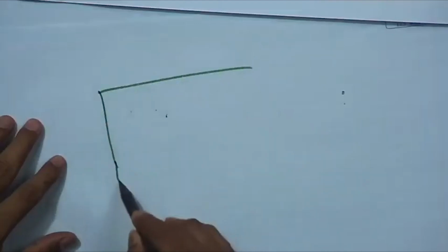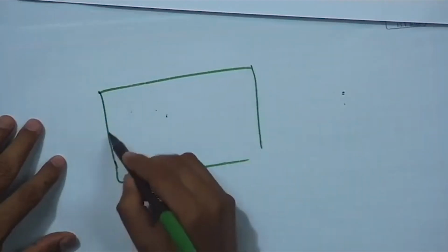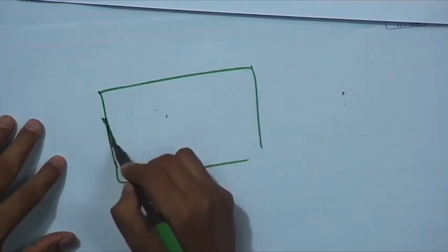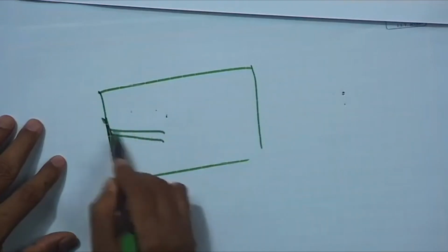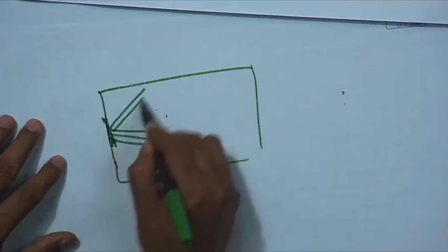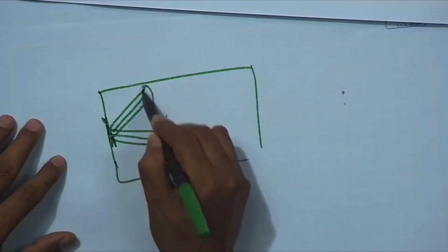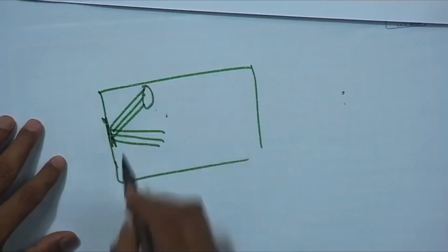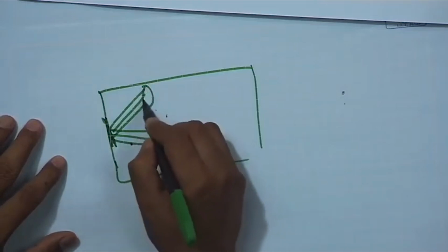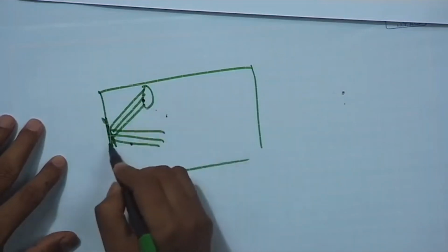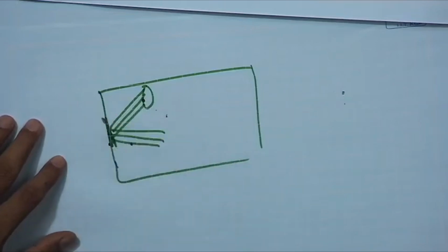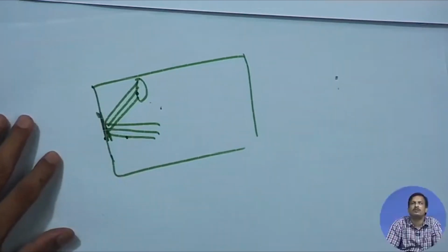One is called focusing of sound. Suppose I want to design an auditorium, an acoustic room like this, and I put a regular reflector here. If a sound comes in this direction, it will go in this direction. So, this portion will be focused. I do not want the focusing of the sound. I do not want a regular reflection on the surface.